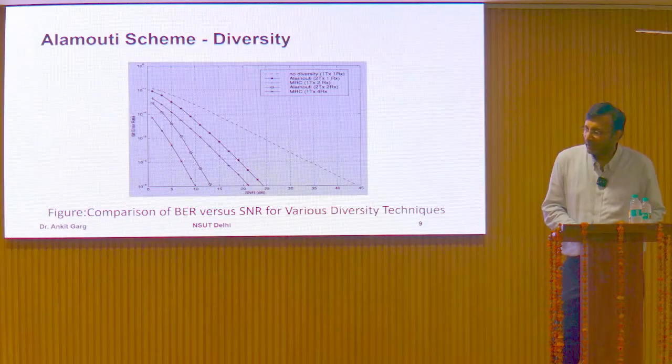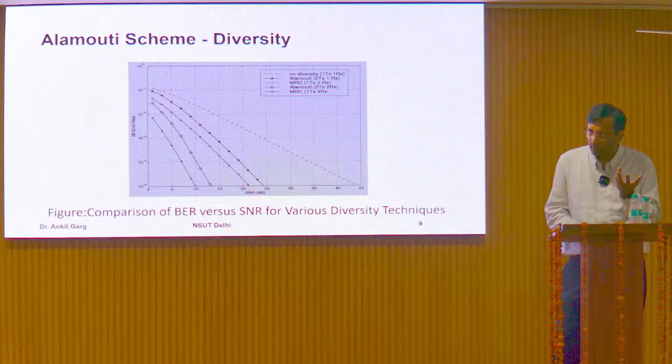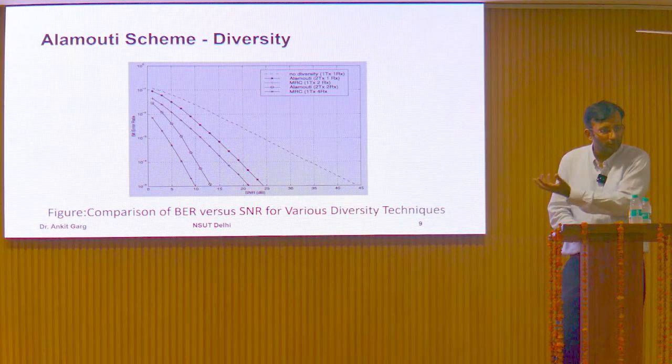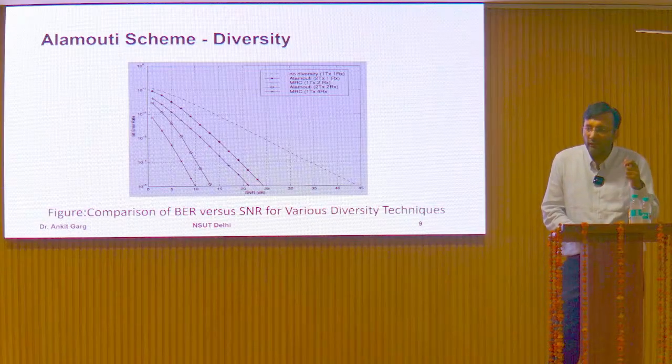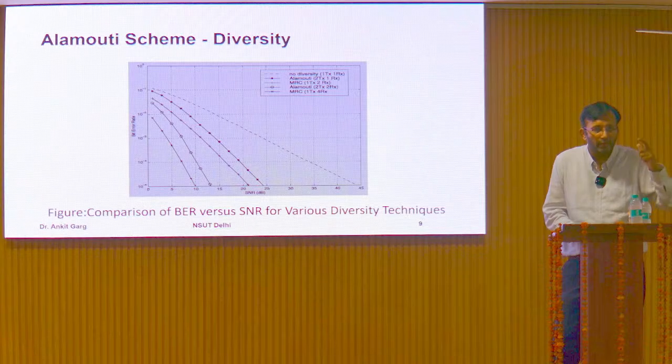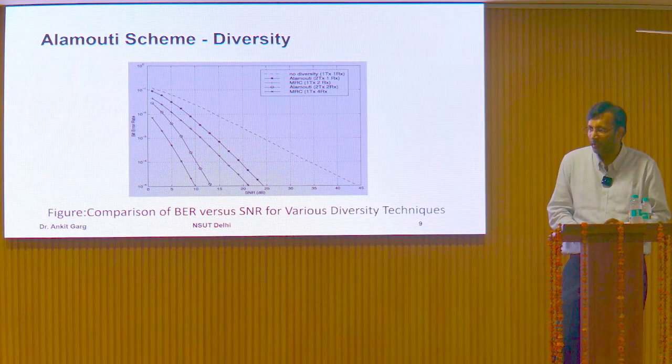You may say it seems like if we have the option of full channel state information acquisition, why don't we choose the simple beamforming and MRC technique here? But what about when we have a large number of antennas, like 100 or 1000 antennas? It would not be possible for us to estimate the full channel state information for all the antennas, right?